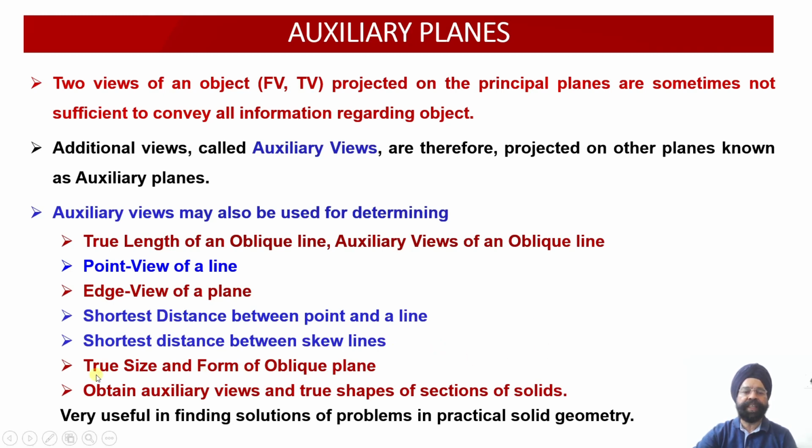Similarly, we have already discussed evaluation of the true size and form of the oblique plane. The other application of the auxiliary planes is obtaining the auxiliary views and the true shapes of the sections of the solid. This we will be discussing while we are having discussions about sections of the solid. The auxiliary views are very useful in finding solutions of problems in practical solid geometry.